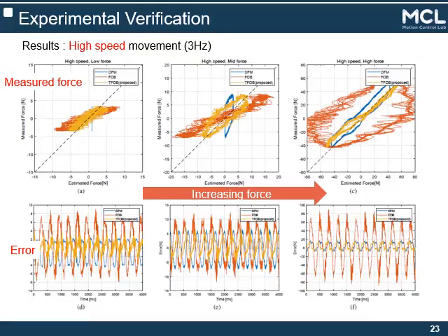This is another experimental result when fast interaction force is added with 3 Hz frequency. Similarly to the previous result, the spring deformation-based result shows a poor estimation result when small forces are added. And the estimation performance of the force observer becomes even worse with this fast force application. This is due to the low-pass filter characteristic embedded in the force observer. In this experiment also, TFOB always shows the best estimation performance among all 3 approaches.